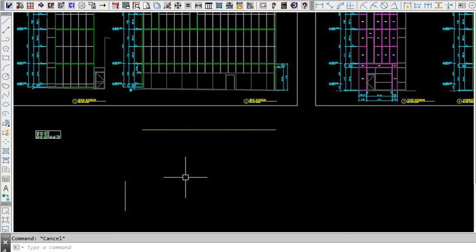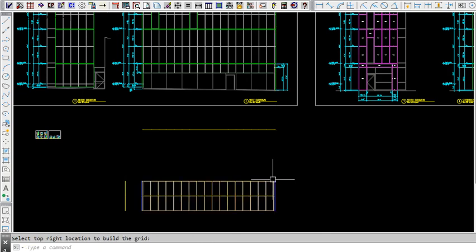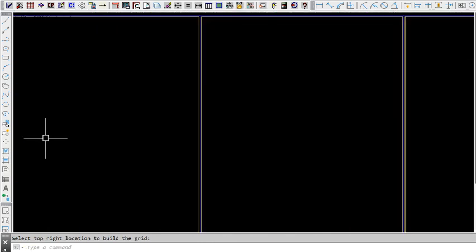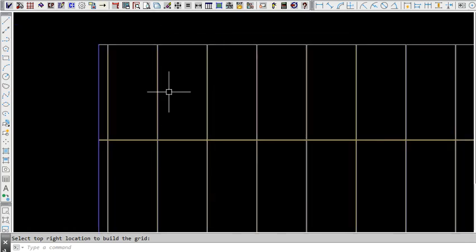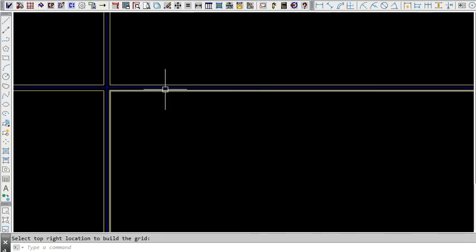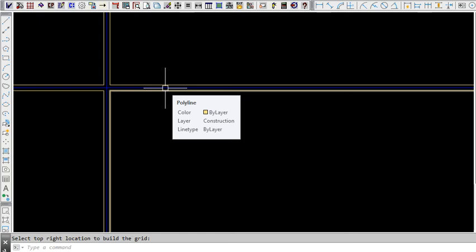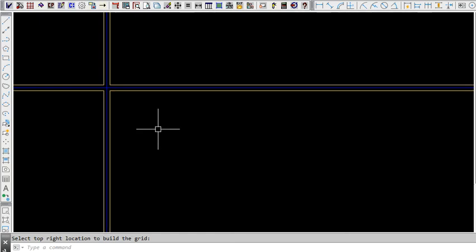So now we're going to do it just to show you how you can use that P-grid utility, which is just projecting a grid. And then we'll come over here and line it up. And then that way you get a whole group of panels real fast. You see how the shapes are already in there. The blue line is actually the center line of the reveals, which you could use for spline and takeoff material.